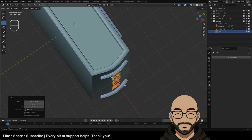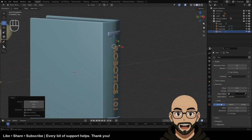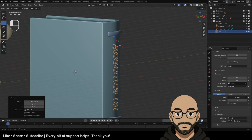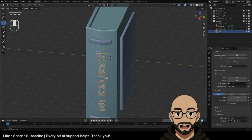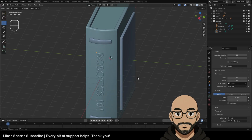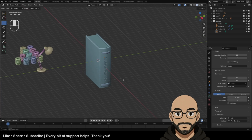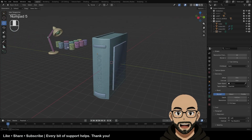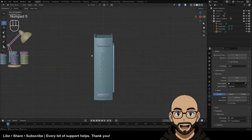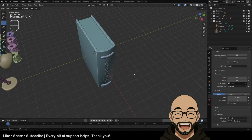And just add some extrusion. You can of course change the fonts, add some bevel, whatever you want. I think that looks nice. Something like that, it just kind of sits there. You know, we have a little book. It's not so little compared to the lamp. Sorry, I went into orthographic mode. If you want to work in orthographic mode, you hit 5 on the numpad. Or if you ever get stuck in that mode and you're wondering what's going on.